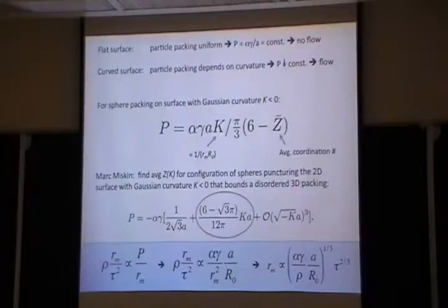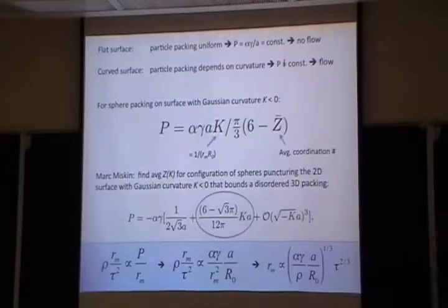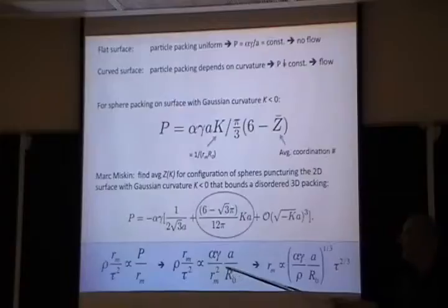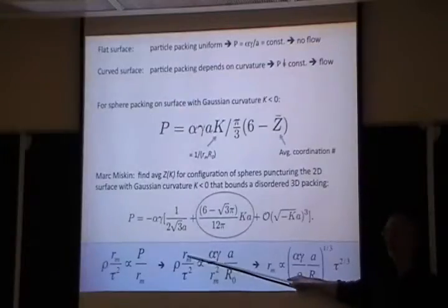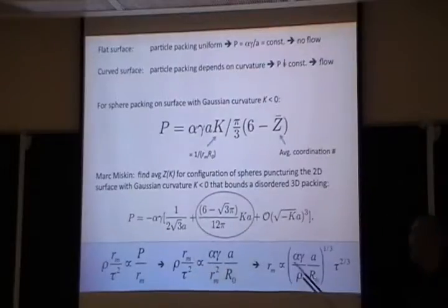And one thing I forgot to say: viscosity is irrelevant in here, right? The only thing that opposes this caving in is inertia, if the part is being pushed out. So this is the inertial part on the left side, and this is this meniscus-driven pressure on the right side. Now you reorganize that a little bit, bring that over. You see there's an R, there's an R squared, that gives you an R cubed. And then you get a T squared here. So out of this emerges exactly the scaling law.